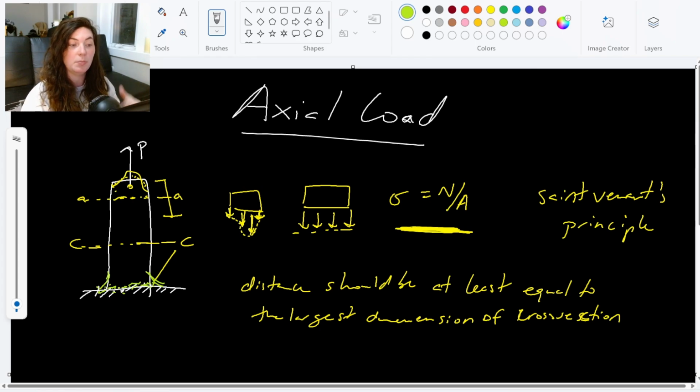You might have noticed if you did the Play-Doh lab experiment that I have up, that there was some deformation more so at the binder clip where you clip onto the Play-Doh. It was more likely to snap there because that's where the load was. That's where more deformation was occurring than if you were to look farther down on your little strip of Play-Doh. So it's just something that we keep in mind. We know that it's there, but it's generally small enough that we can ignore it. It is generally causing such small localized deformations that they have a very, very small effect on what we're doing.